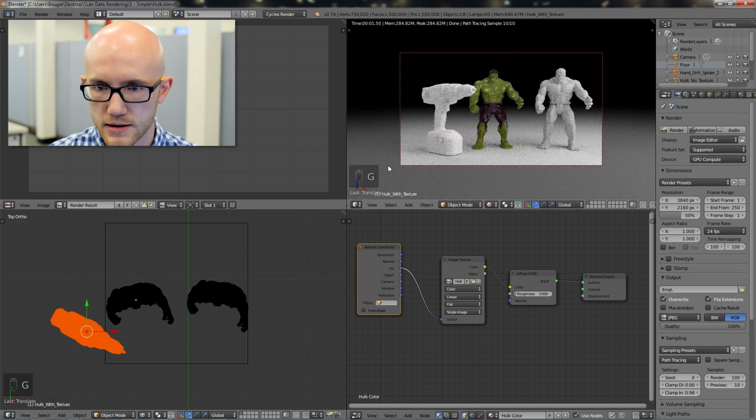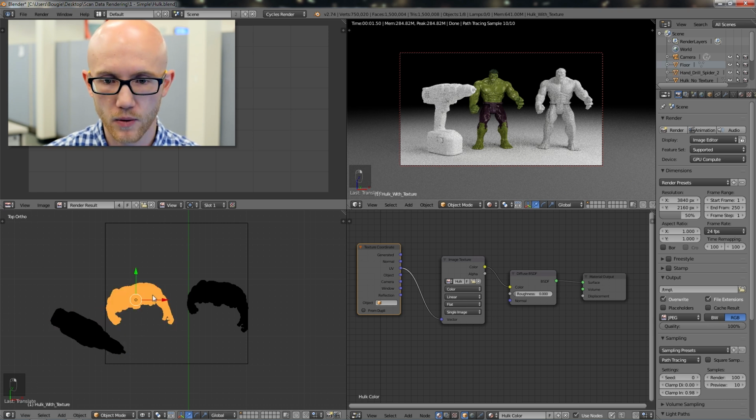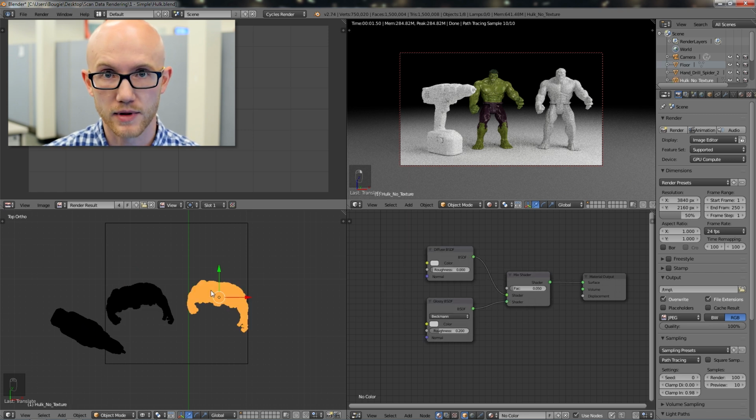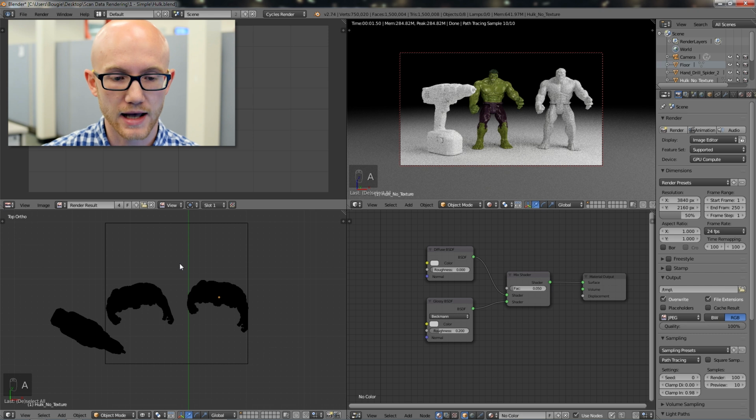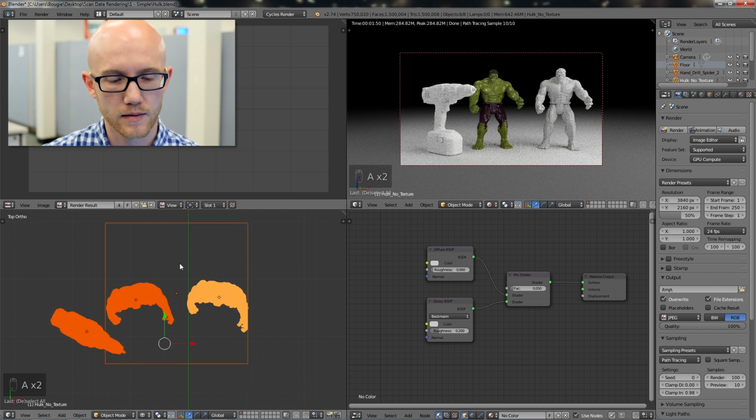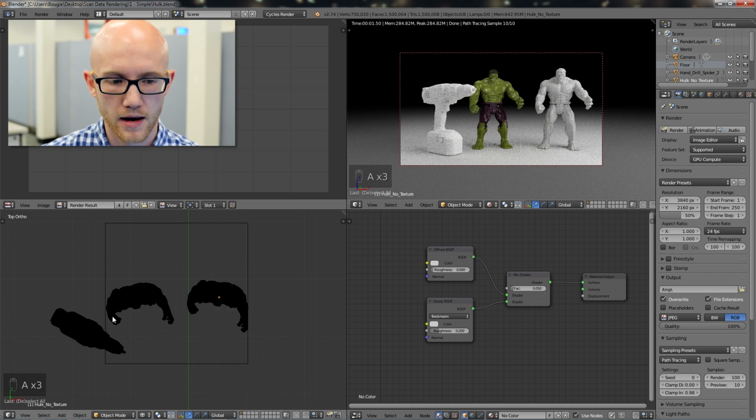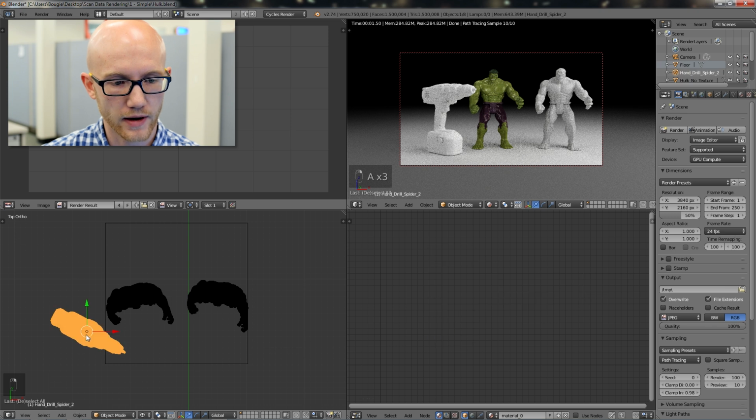Okay, so now you can see in this top right corner here, it's the model, but it doesn't have the color data. So what I'm going to do, when you first import something and you want to apply color, you actually have to deselect that by selecting something else or pressing the A key. So when you press the A key, it will select everything. Press it again, it selects nothing. Now I'm going to right-click and select my drill.